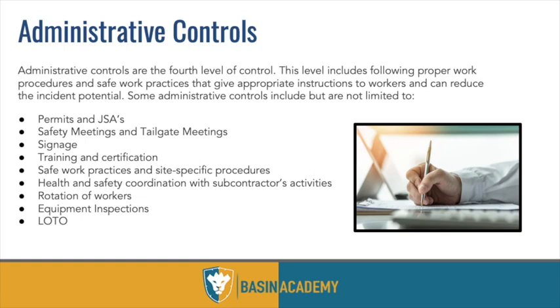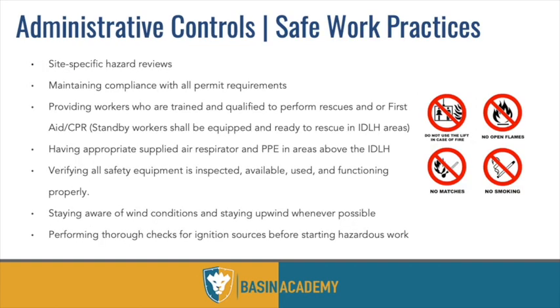So safe work practices, these are extremely important. I don't think a lot of people take into consideration how important these tools are, but planning the work, thinking through everything that can go wrong, even if it's very low likelihood. Start at the worst case scenarios and then work your way towards what you're about to do, and then figure out ways to prevent those things from happening. Barriers, ventilation, fans. There's a lot of different stuff. Well, what if this happens? Well, let's get a fan out here so it disperses it quickly. Whatever you have to do.